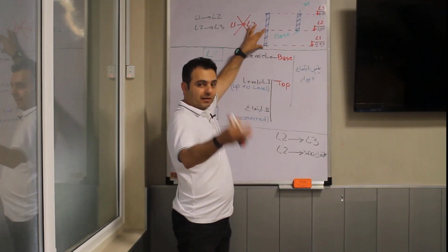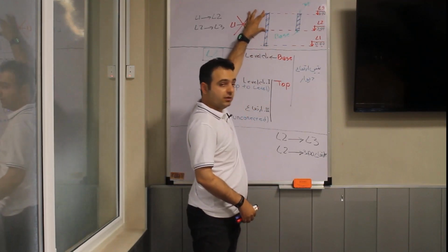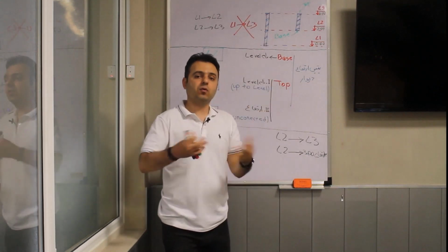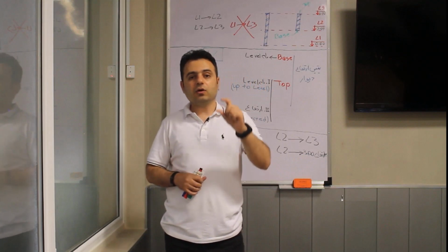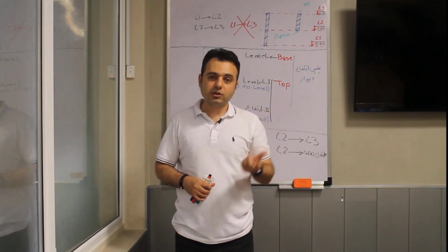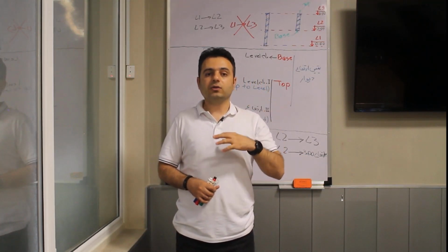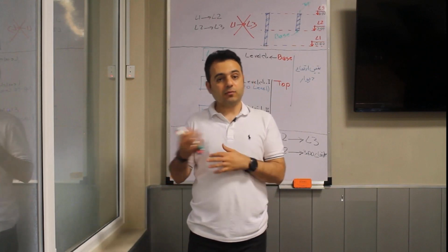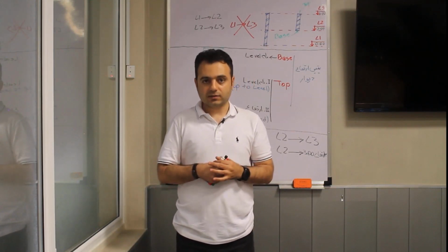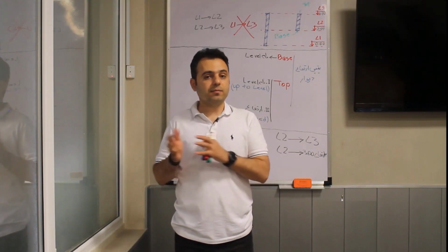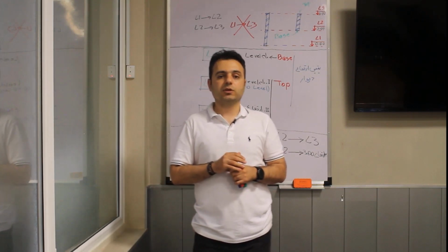The first code, for example, is executed in the 5th week, and the next one is on the 10th week. You see? So you should draw the walls in the floors separated from each other so that they can receive different execution codes and different times to be built, which is for 4D.